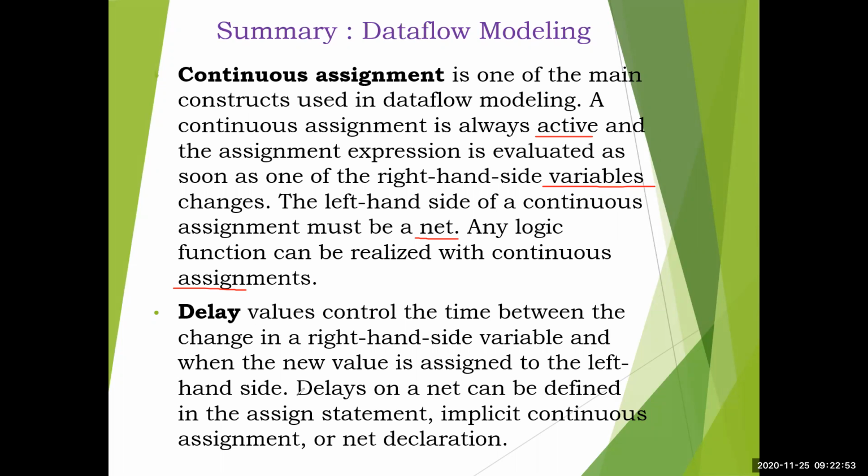That is the part of delay value specification, and delays on a net can be defined in the assign statement. As we have learned three types of assign statements, in the same way we can use the delay in the regular assign statement, the implicit continuous assignment statement, or the net declaration. This is what you saw in the first part.